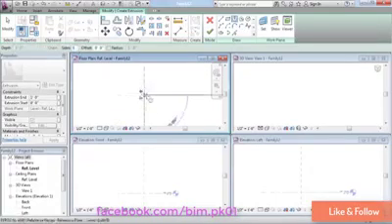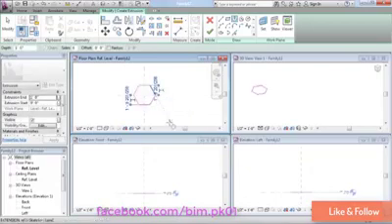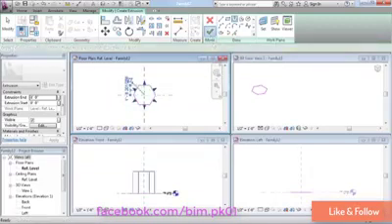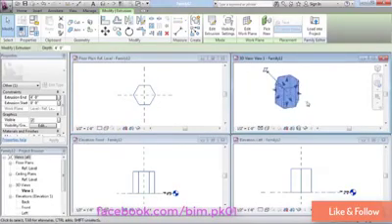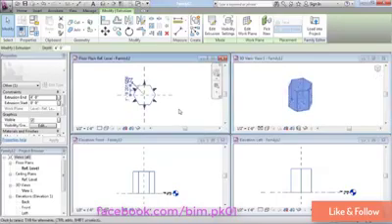I'll draw it right here at the center and maybe out to a 2-foot radius. What I've been doing up until now has been ignoring the depth parameter. That is controlling how tall this extrusion is. And so you do have a few options. You can actually change the depth before you finish the form. Maybe I want this to be 4 feet tall, so I can plug in the number 4 here before I click finish. And you'll see that the height of this thing will be a little larger than what it has been previously. But of course, you can always change that depth later.